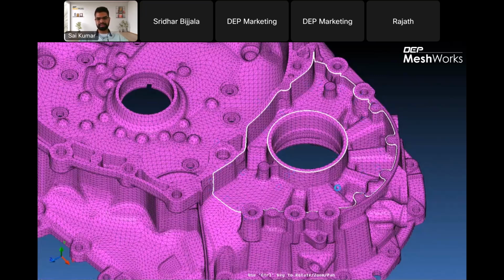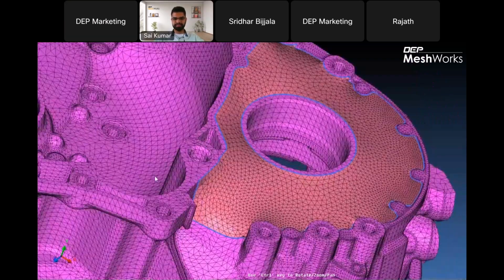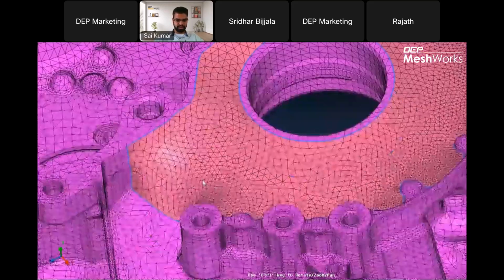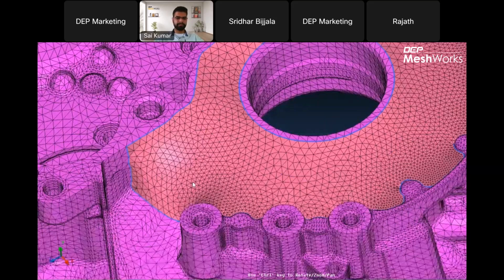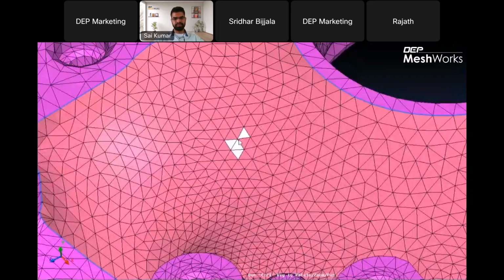After it's created, we can adjust the cover using the adjust cover option. So this is how the design space cover is created, which is nothing but a 2D shell cover. We can adjust the cover dimensions accordingly by selecting a few elements in the cover, and we have all these options on how to proceed for the adjustment, whether we offset, rotate, scale, or translate.